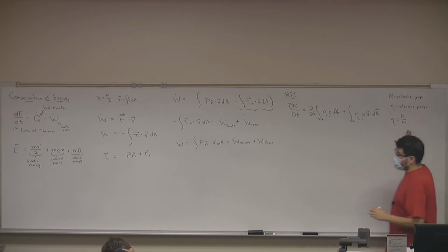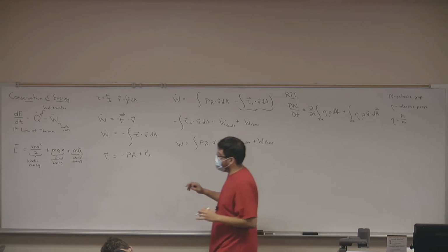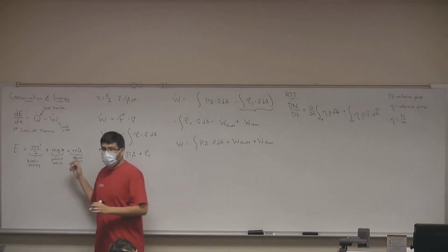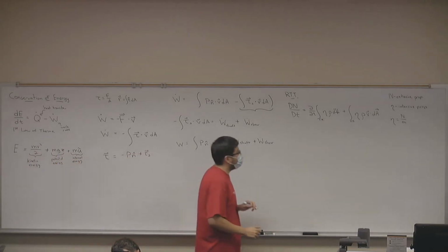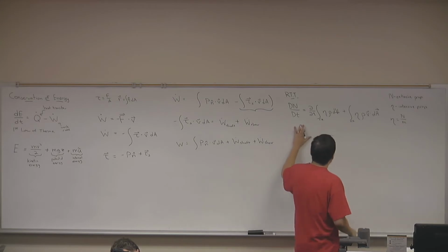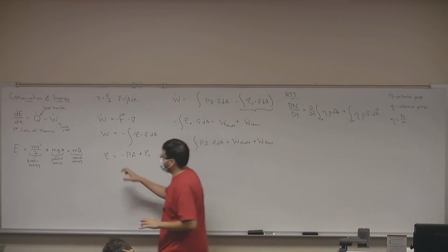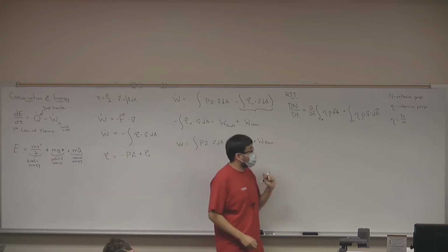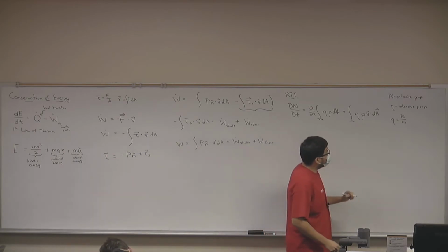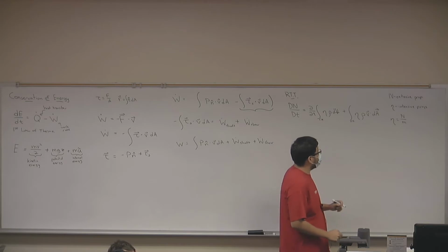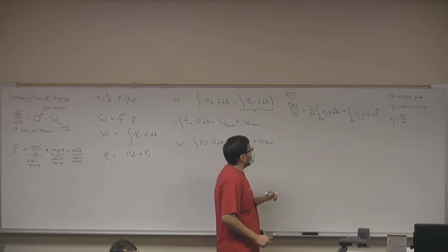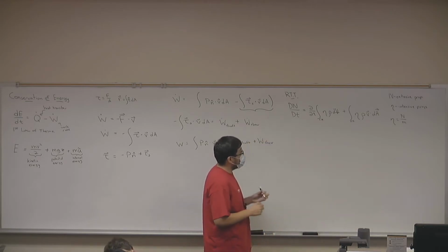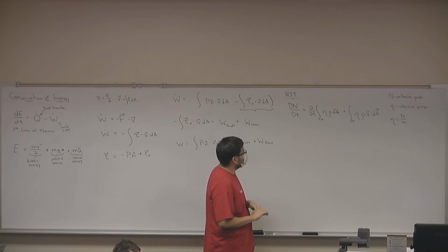And hopefully, I hope that you now start to see why I wanted to express my energy as functions of mass. Because if we want to apply this Reynolds transport theorem to find a relationship for the first law of thermodynamics in control volume terms, we need to know what the extensive property and what the intensive property are. So let's do that. Let's apply the Reynolds transport theorem to the law of conservation of energy.